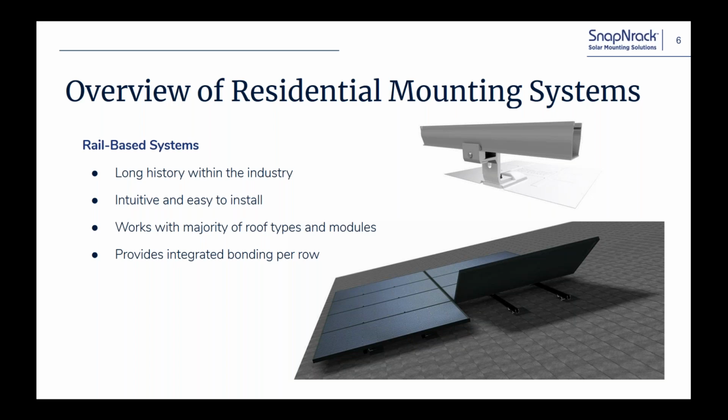But basically, that was the goal, is to get something on the roof to attach the modules to, because you can't attach them to the shingle or the tile or whatever it is. So get some rail up there, get some modules on there. It's fairly straightforward. You create a platform to drop the modules on, you clamp the modules to the platform. Pretty easy to train people to do that,